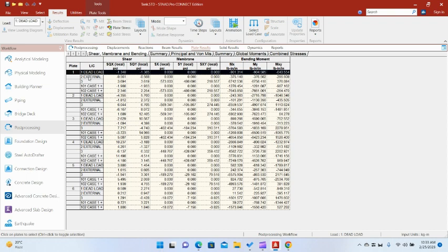These are the load cases, load case number 1, 2, 3, and their combinations. And these shear forces, which are shown over here, SQX, SQY, then for membrane, SX, SY, SXY, and the bending moment, that is MX, MY, and MXY. The units are, of course, stresses are in PSI, all stresses, and the moment is pound inch per inch.